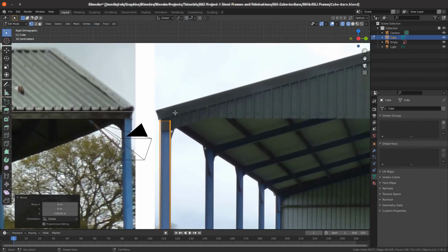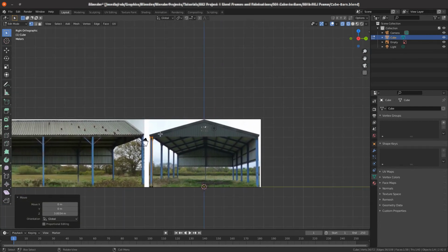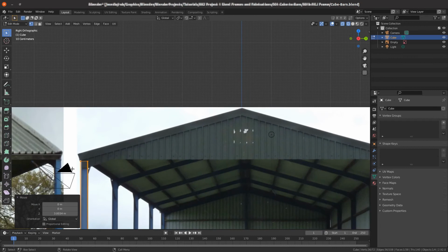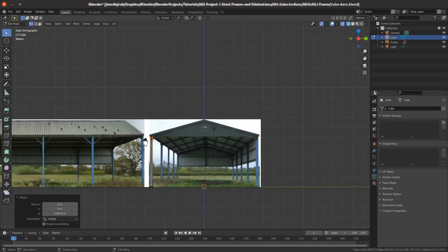just below the flashing that's on the side of this portal frame. We're going to put a curved roof on, but the curved roof has also got purlin sitting on top of it, so the top of the curvature will be higher than the top of the RSJ. In fact, if you look at the side view, we're almost spot on with where the purlins sit on top of the RSJ at that point. Just Z and go back into solid.